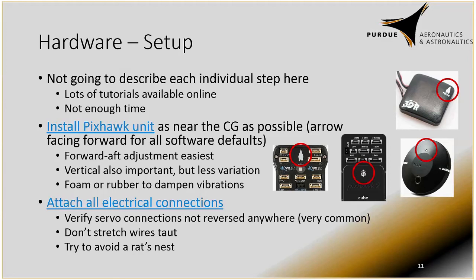All of your airspeed sensors, your servos, your power module, your GPS, all of that. Make sure everything is attached correctly. Make sure nothing's reversed. I'll get to that in the next slide. Don't pull your wires taut as you have them installed, and try to avoid a rat's nest. It'll make it a lot easier on everybody if you're not trying to dig through 15 different wires trying to